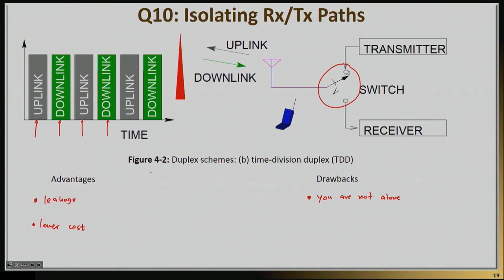And because you don't have your own dedicated band, you're actually listening over the entire spectrum, you can't prevent people from transmitting in that entire spectrum. So whenever you're close to maybe an unintentional transmitter, your receiver will actually suffer a lot. You don't have your own guarded band now. So that means that your noise level will suffer in general. And not only will it suffer, but it will be relatively unpredictable because you can't prevent people from being there.